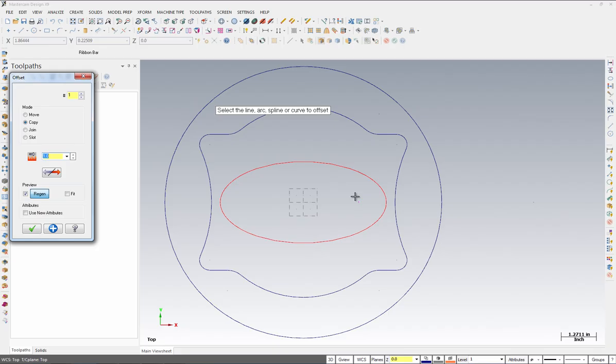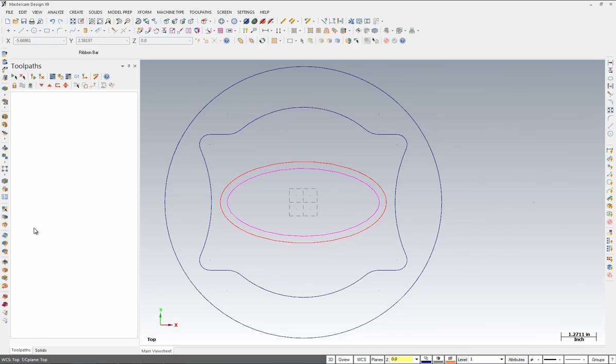You can see that things didn't really change here, as we need to input new values. Change the distance to 0.25 and hit Enter on your keyboard. Make sure there is only one geometry that you are copying over. And select OK to exit the dialog box. Again, since we used an X-form option, we will need to clear our colors.